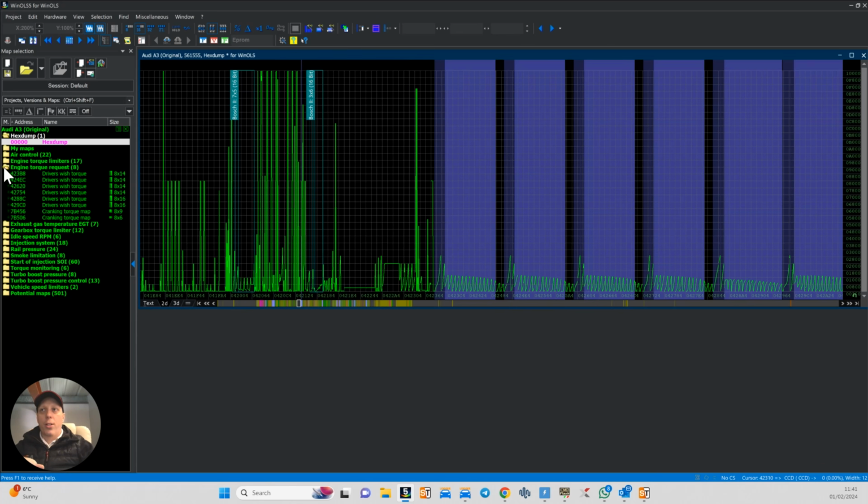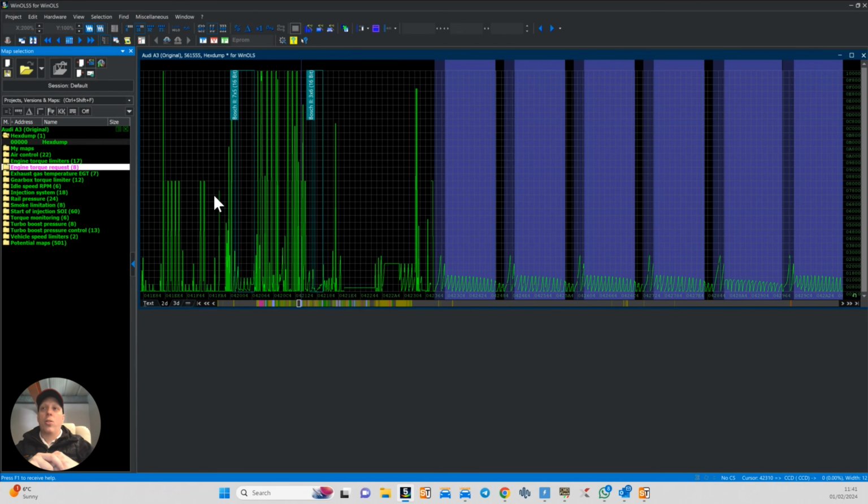It's pretty good. There's a lot of maps out there that it covers, and to be fair, I've sat and built stage 1s and stage 2s using their map packs, so they are quite good. The only thing I would say is to know what map you're in by logs and things like that. Get used to logging cars first. If you're looking at tuning, you're probably better off logging cars first than making changes. Build an understanding of what's going on, what the ECU is seeing. So when you're making your changes, you can physically see them as you're changing them based on the logs.